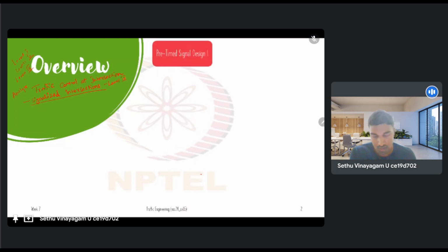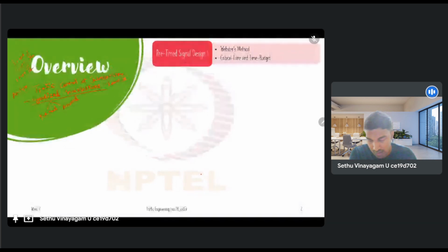In the first lecture, we looked at pre-timed signal design. Within the signalized control, we have pre-timed and actuated controls. In pre-timed, we have the signal cycle length. Every characteristic that belongs to the control, like the cycle lengths, the phase sequences, and the interval lengths, will be fixed. It doesn't vary from cycle to cycle. So that's what we have in the pre-timed signal: fixed characteristics.